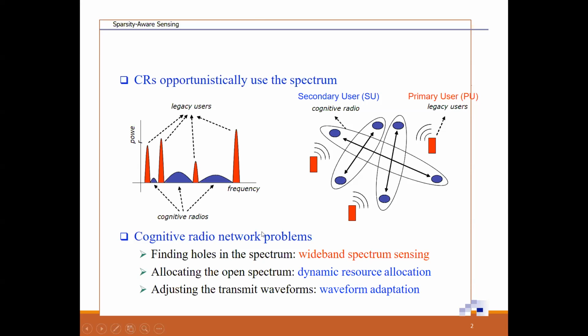So what they have to do is keep on sensing the spectrum every now and then whenever they want to communicate and occupy the band that is free. Moreover, once they have occupied a particular band, say there is one cognitive radio user who is a secondary user. He knows that this band is free, so he started to communicate here. He cannot keep on communicating in the same band until his communication is over. No, because suddenly another primary user can come into the picture to occupy this band. So the secondary user has not only to communicate, it also has to keep on sensing the spectrum continuously, to see whether any of the primary users is coming to occupy it or not.